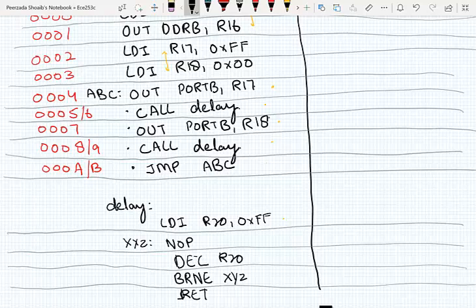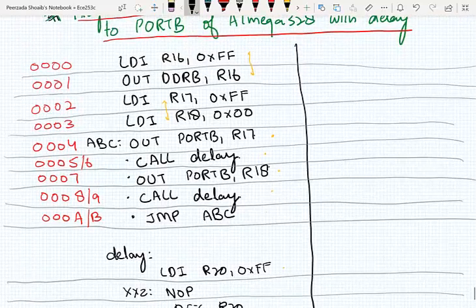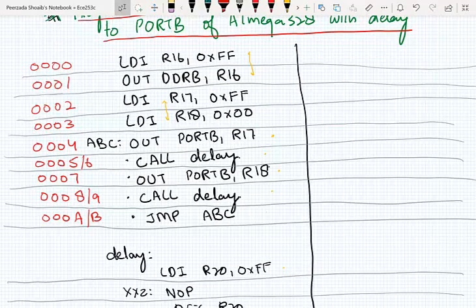It's as simple. So now the first question that arises: I have given the address locations where finally the opcodes of these instructions will be burned. Most of these instructions are 2 byte instructions, 1 word instruction. But call and jumps, they are 4 byte instructions. So the opcodes of every instruction will be stored something like this.